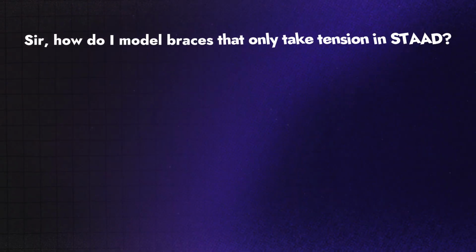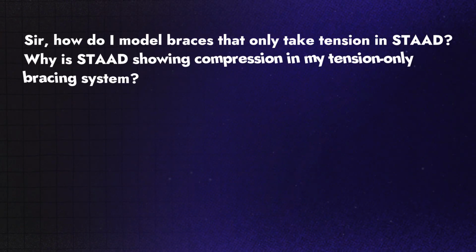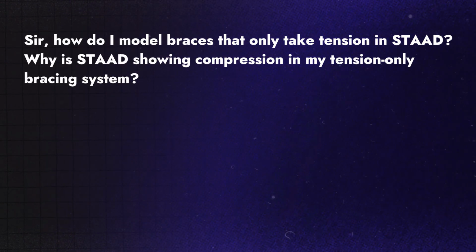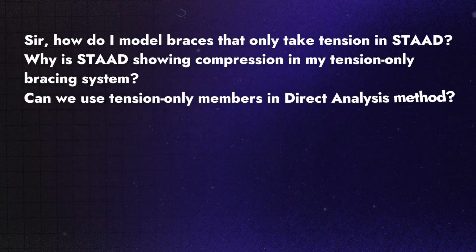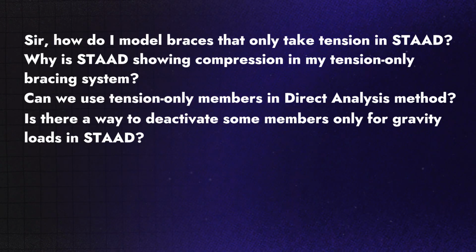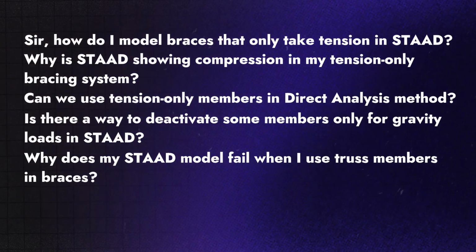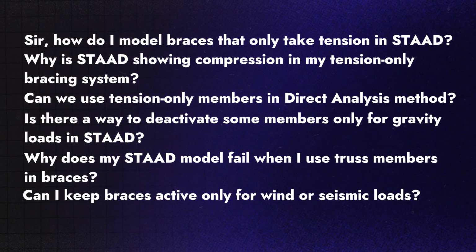Sir, how do I model braces that only take tension instead? Or why is STAAD showing compression in my tension only bracing system? Can we use tension only members in direct analysis method? And the other question was, is there a way to deactivate some members only for gravity loads in STAAD? Or why does my STAAD model fail when I use truss members in braces? Can I keep my braces active only for wind or seismic loads?